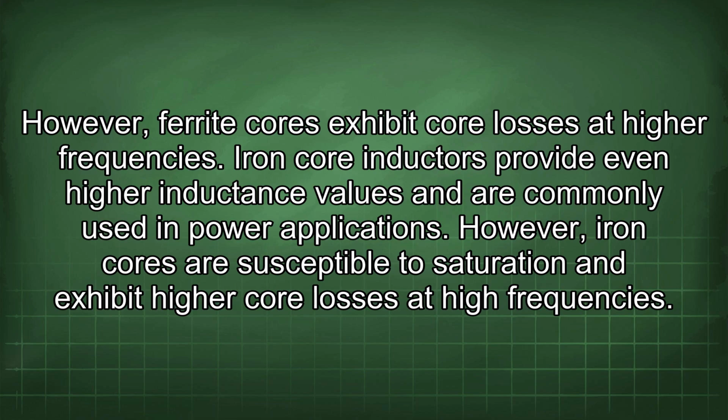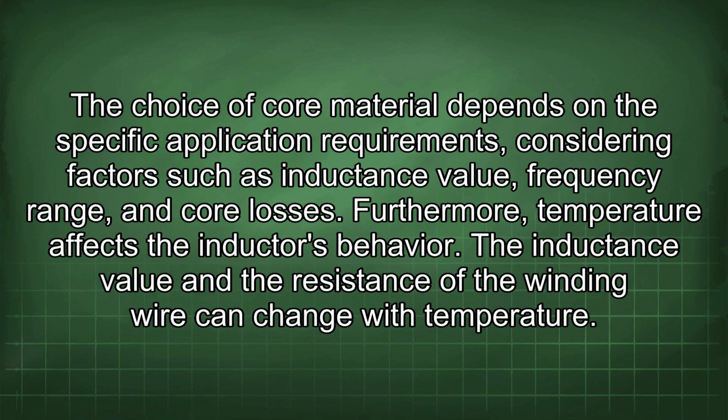However, iron cores are susceptible to saturation and exhibit higher core losses at high frequencies. The choice of core material depends on the specific application requirements, considering factors such as inductance value, frequency range, and core losses. Furthermore, temperature affects the inductor's behavior. The inductance value and the resistance of the winding wire can change with temperature.